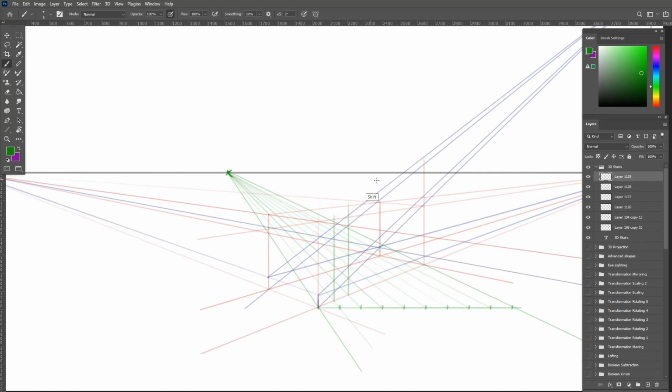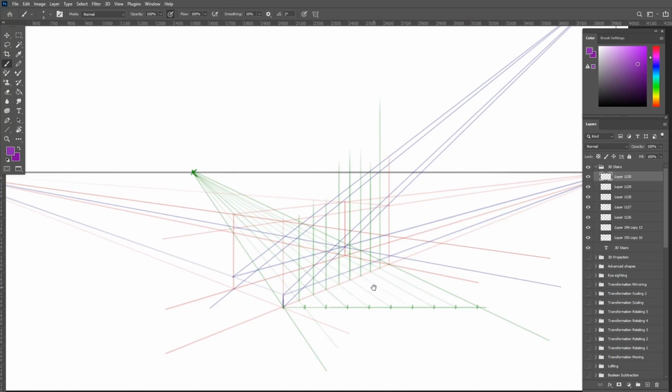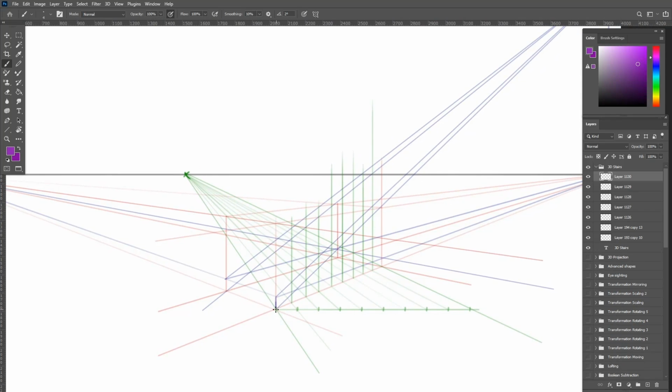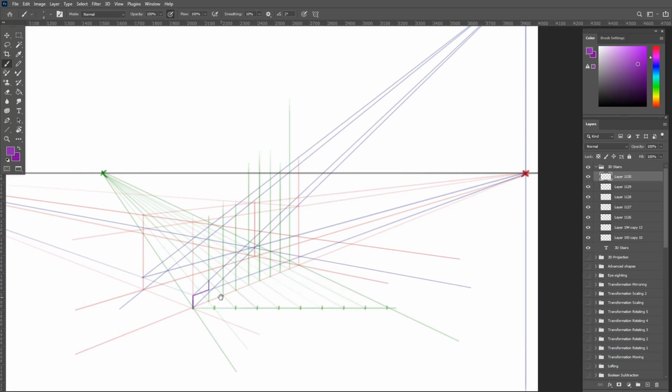From there, I draw the vertical line to divide the side face of the bounding box. Now it's time to draw the side projection of the stairs following the intersection lines between the vertical divisions and the diagonal line toward the vertical vanishing point. Once you connect the vertical line, you can extend it back to the horizon line to draw the top of the step. The step stops at the second angle line on the bottom of the step above it.